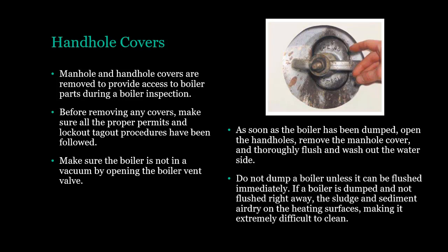As soon as the boiler has been dumped, open the handholes, remove the manhole cover, and thoroughly flush and wash out the water side. Do not dump a boiler unless it can be flushed immediately. If a boiler is dumped and not flushed right away, the sludge and sediment air dry on the heating surfaces, making it extremely difficult to clean.